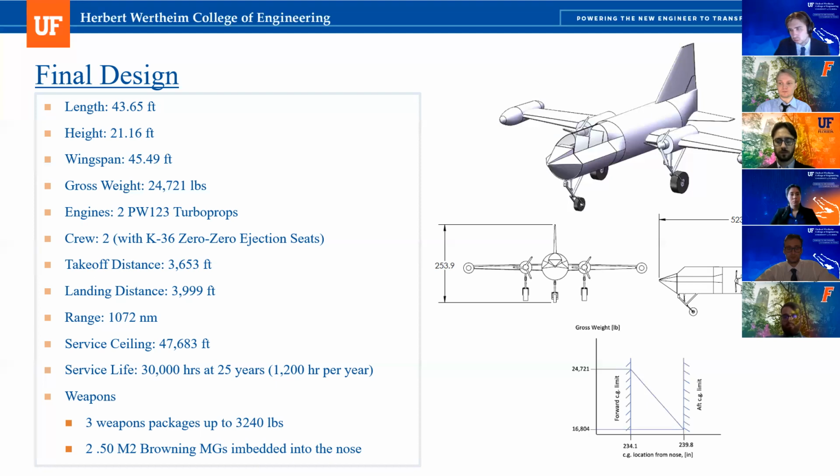of course, weight estimation and a center of gravity estimation, because that is basically for the stability and control analysis, right? So we want to make sure that our design aircraft, the whole thing, has longitudinal stability, lateral stability, and directional stability, right? So for that part, you need to make the derivative of each part within the reasonable range,